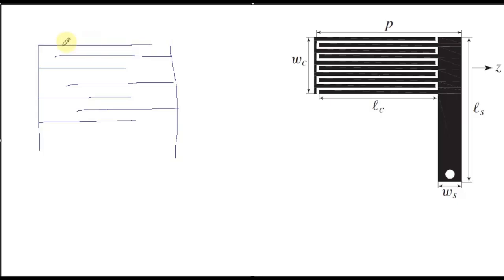And here, in this capacitance portion, they are all connected with a conducting wire. This wire will behave like an inductor, and similarly there is a stub. It also behaves like an inductor. So this portion is the inductive portion, and there is a via, which is also a conducting portion connected to the ground. So it makes a short circuit in between this plate and the ground plane.